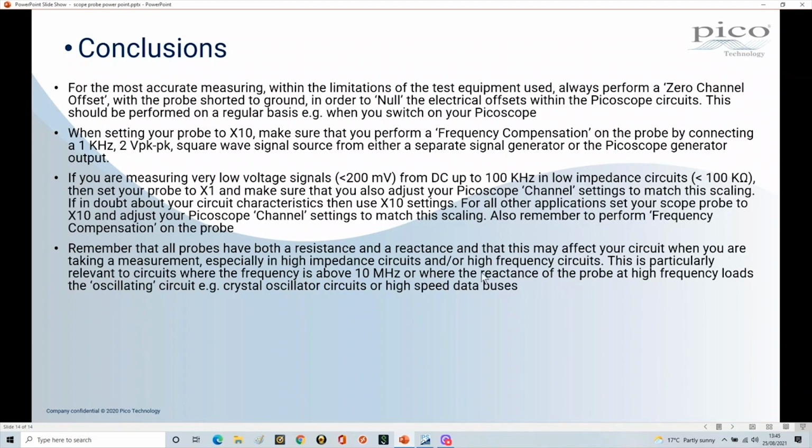This is not a problem when you're using a times 10 probe and your bus might be running at sort of like maybe, I don't know, 1 megahertz or 10 megahertz or something. But if you're trying to run something at, you know, 100 megahertz, then you've got to make sure you've got the right test equipment to be able to perform that kind of task. And you may want very special types of probes to actually monitor that to see what's going on, okay?